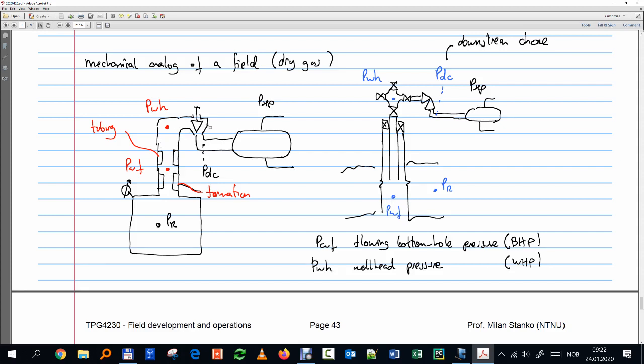But essentially what I'm saying is that these usually remain unchanged during the life of the field. The only thing that will change is the things that I can modify, that I can vary, and that will typically be a choke, or a booster, a compressor or a pump. If you see there, you have some loss of energy from that formation. Some of it will be unchanged, but some of it I can change or modify, either to give me more rate, which is usually the case, or to keep production at a certain level, which might be desirable for some reason.